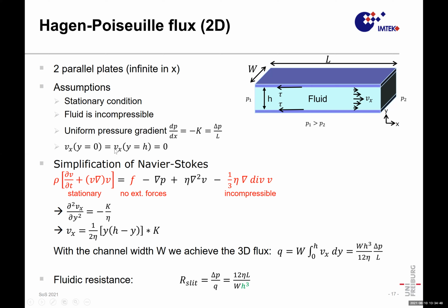And then we check velocity in one direction. And we say also that the side condition, we have no drag flow at the wall sides. So there's zero at both ends. There is, however, also a flow where you generate a slip at the wall, a so-called slip flow. Then this condition would not hold, and we will see such situations later. They are realistic, but this is the very simplest one.